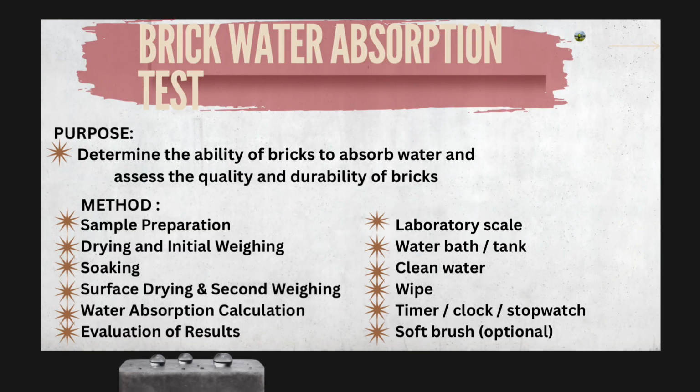Brick water absorption test. Purpose: determine the ability of bricks to absorb water and assess the quality and durability of bricks. Method: sample preparation, drying and initial weighing, soaking, surface drying and second weighing, water absorption calculation, and evaluation of result.